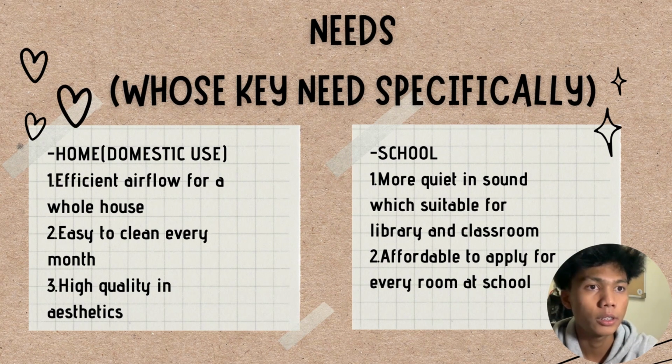Typical people only experience fan problems once it has been in use for many years. About 7 out of 10 people complain about the same problem, such as noise, which can be caused by a loose part or a damaged motor. Fan speed issues are also common and may be caused by the switch or a capacitor. Additionally, a fan may wobble or shake due to an unbalanced blade or a loose screw.